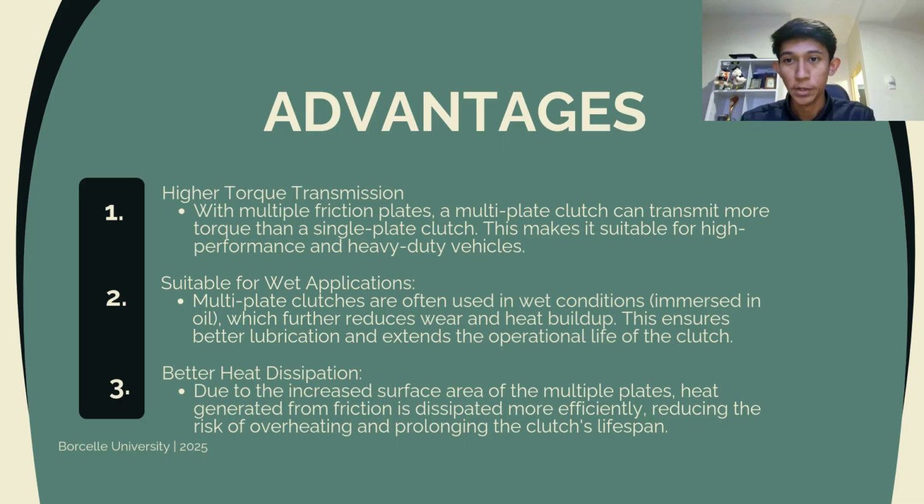Next up, we'll be jumping on to the advantages of it. So we have three of them. One of them is high torque transmission. With these multiple friction plates, they can transmit more torque than a single plate clutch, and this makes it suitable for high performance and heavy duty vehicles.